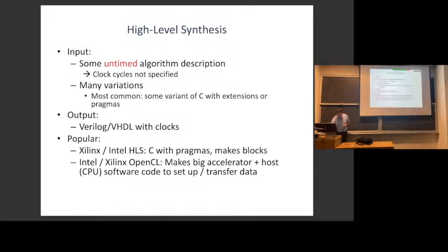Okay, so there's lots of different ways to do this stuff. So let's talk about a domain-specific high-level synthesis tool. And this high-level synthesis tool is useful for streaming data flow. Streaming data flow, as we saw, is useful for, well, one of the things it's really good for is signal processing. Signal processing maps really well to a streaming data flow compute model. So you can go write in HDL your streaming data flow, and in fact, you're doing that in lab 1. You'll do a bit more of it in lab 2.